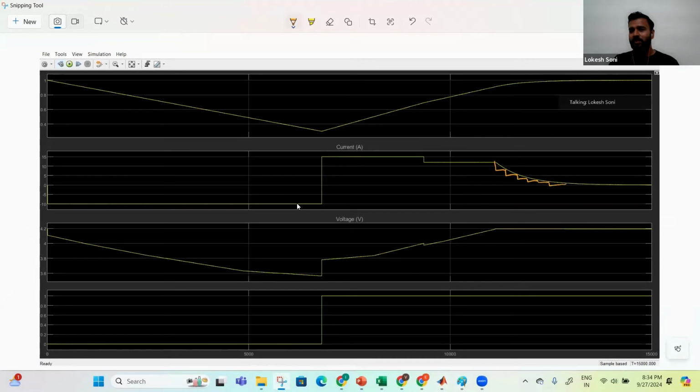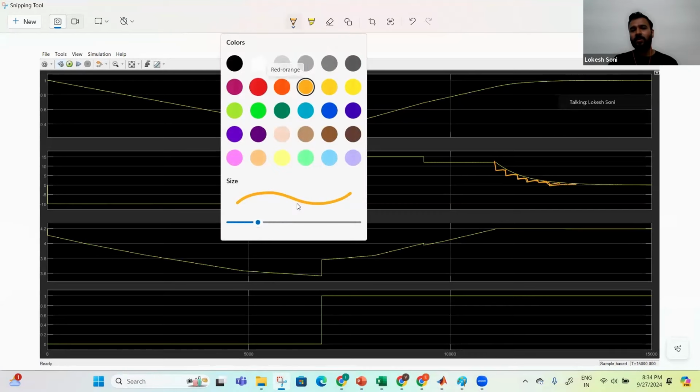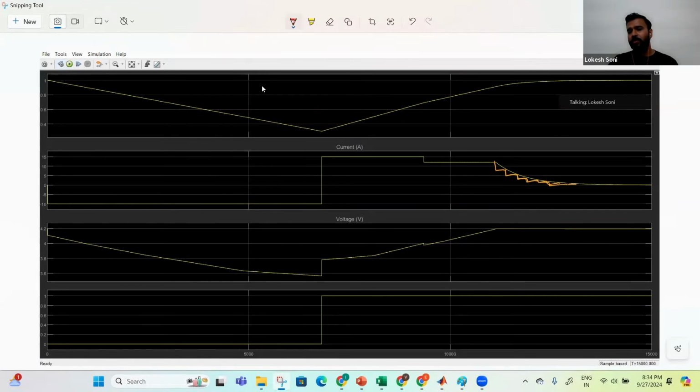What I'm saying is, if you want to avoid the circuitry of voltage control, you can do multiple CCs, and this is how you would do CC and more or less mimic the CV charging. If you just want to dominate the time, here you would be losing some time. What you can do is, with the required safety margins, do it like this so that you would not be reducing the time, instead would be increasing only. If you just want to match the time, initially you can do this, and later when the voltages are closer, you can do it on the lower side. So MCC can be done in many ways. Again, it depends on the requirement.